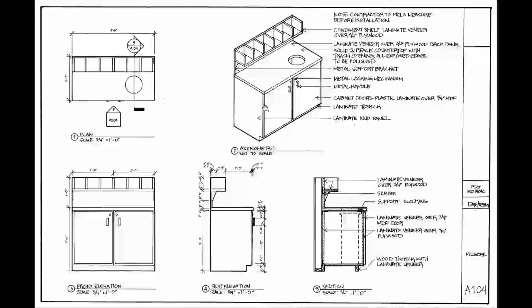So even though there's a change of plane on the door and there's a change of plane on these hardware pieces, and there's a change of plane for these faces here, it just won't work with a 0.3. So you've got to go down even a little bit thinner.